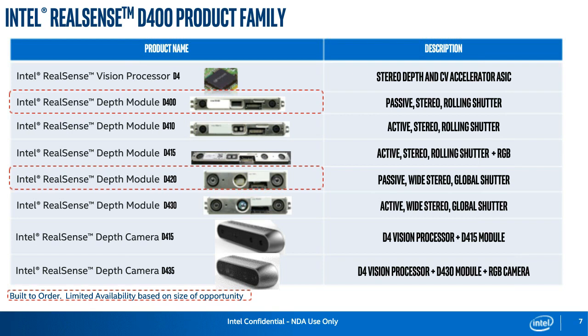We'll start off with each of these being a stereoscopic camera. What that means is there are 2 imagers that take in the image. They work very much like your eyes would work. If you would take your thumb and extend your arm to arm's length, close your left eye, look at your thumb, then close your right eye, and then open your left eye and look at your thumb, you can see a shift in the vision. What happens is if you use mathematics, a great algorithm, you can determine depth to each point. This is what we do for every pixel that comes in from our camera.